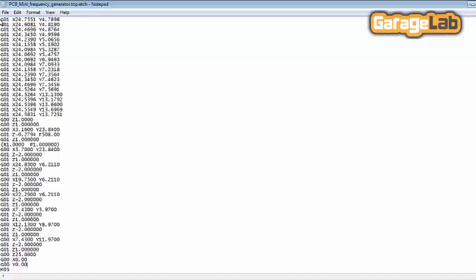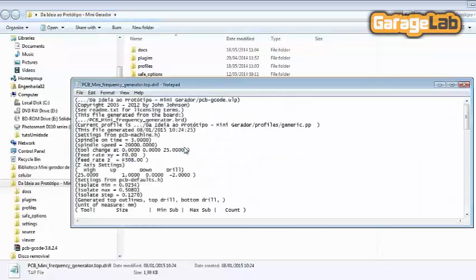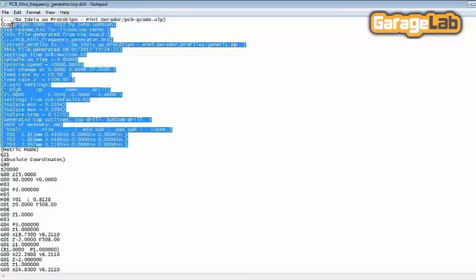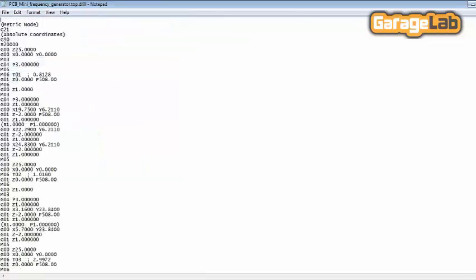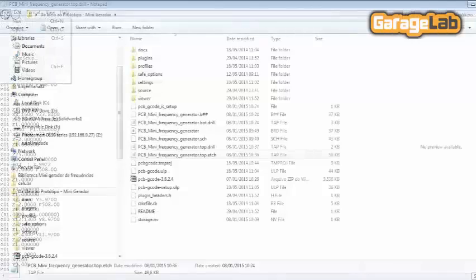We've written these two commands in order to place the tool in the initial position after we have made the design, the outlines, because we are going to do our board in two parts. After the outlines, we will have to change the tool, so we have to restore the initial position to do the holes on our board.